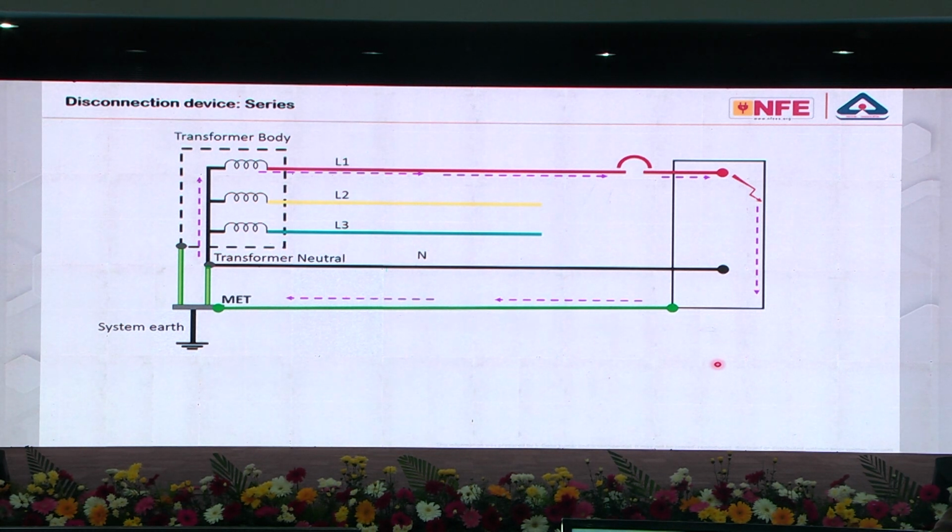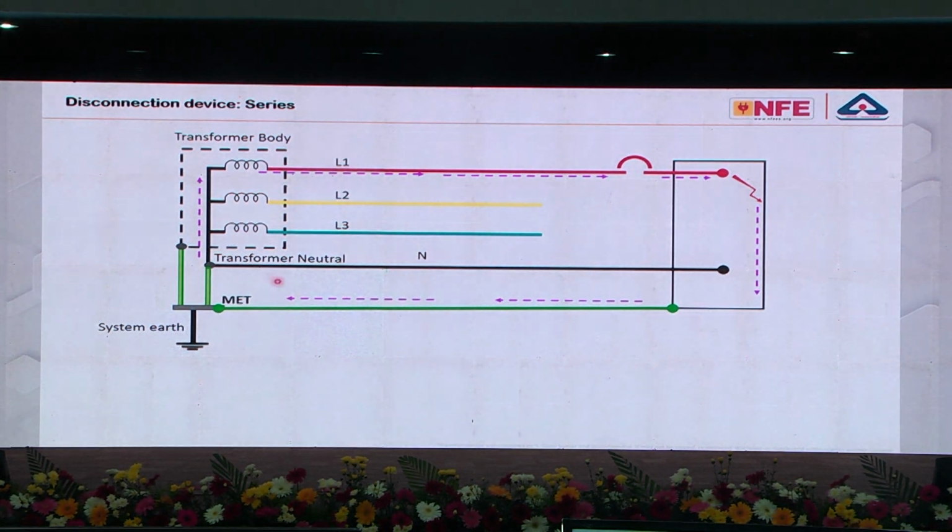Now, in this case, we have a protective conductor. We have a metallic fault return path. If you look at IS 3043 clause 7, it is very clearly explained. IS 732 has written metallic fault return path. Now in the new NEC, we have made some simple pictures with some simple explanations, which is much easier to understand. Now, the fault current is flowing through this particular closed loop.